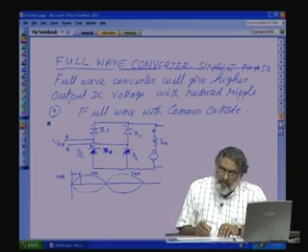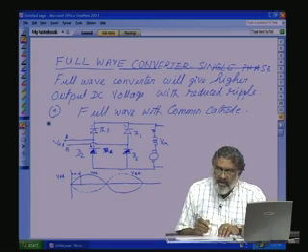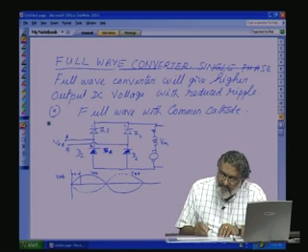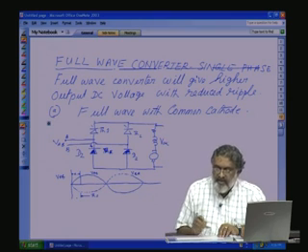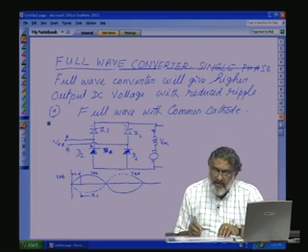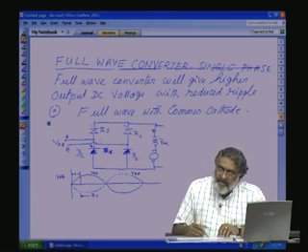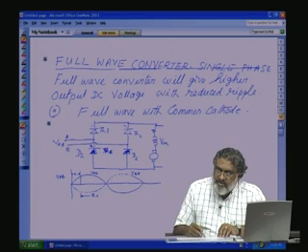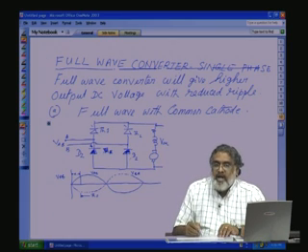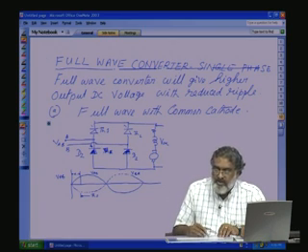So, what will happen? Here we will be firing TH1, from here, where it will come to 0 state. So, let us take TH1 is fired. The moment TH1 is fired, the diode will immediately forward bias because this point will come here and this is already negative, so this diode will conduct.